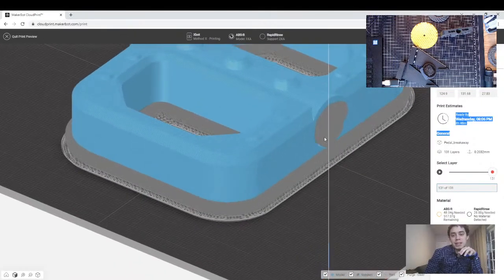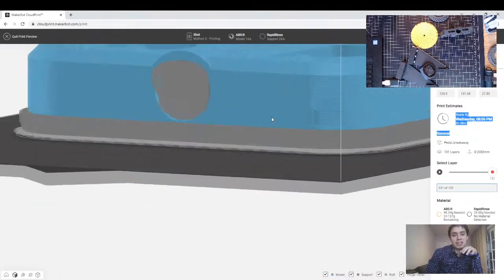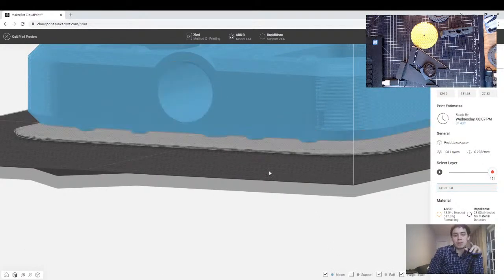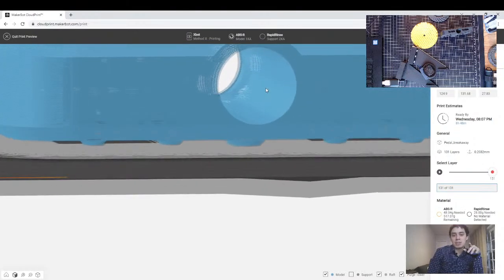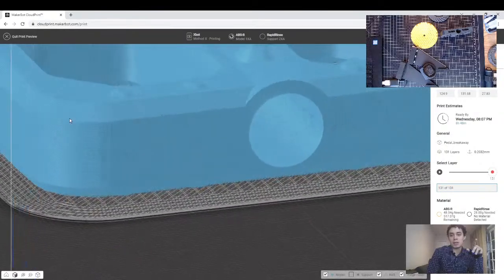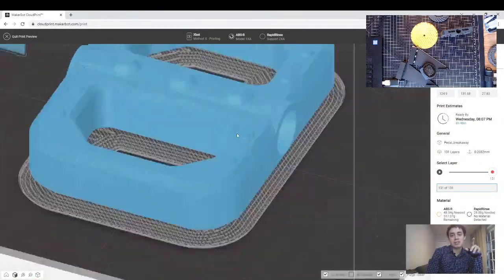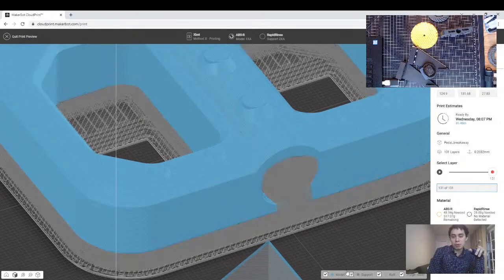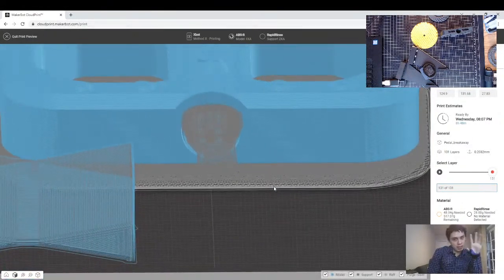I will be getting a lot of support now generated here. In the previous orientation, I didn't have any supports on the inside of the part, so that support might be tricky to remove if I'm not using soluble supports. That's an important thing to keep in mind, especially for something as sensitive as threads. So here are my threads, right? They look fairly clean, but when I add the supports in there, it might be an issue to remove depending on the type of supports that you're using.